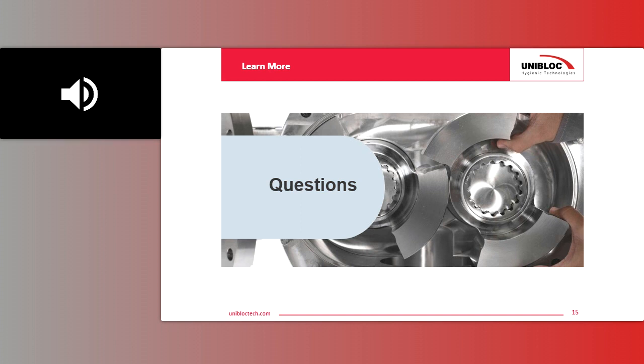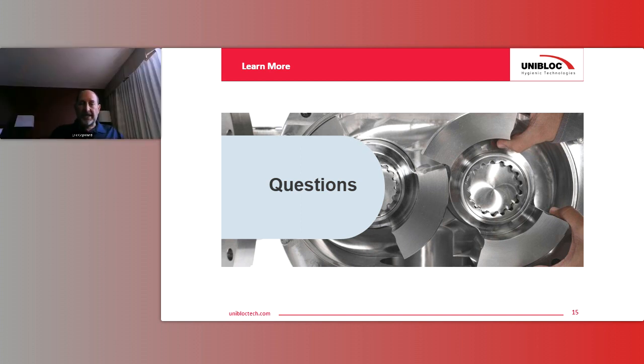Is there a downside if the pump deadheads? It depends on the technology. For most pump technologies, if you deadhead the pump, yes, there is a downside. PD pumps are positive displacement. If something deadheads, most pump technologies will keep building pressure until something gives or breaks. So yes, the downside is something can break downstream.